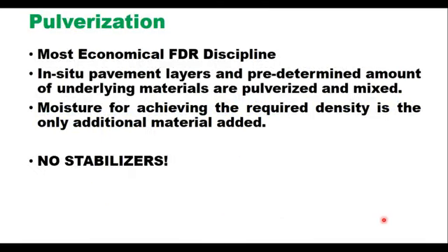Pulverization is the most economical FDR discipline, and in this case in situ pavement layers and a predetermined amount of underlying materials are pulverized and mixed, and moisture is the only additional material which is added to achieve the required density. Here in pulverization, no stabilizer is used.